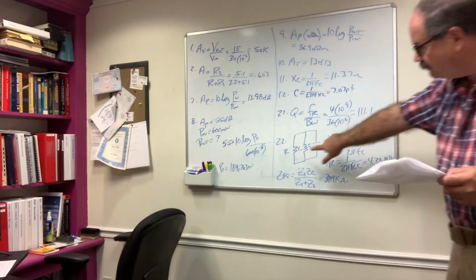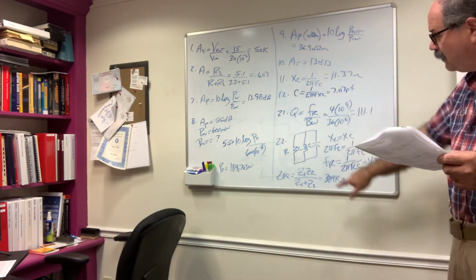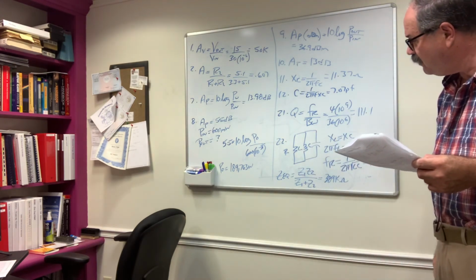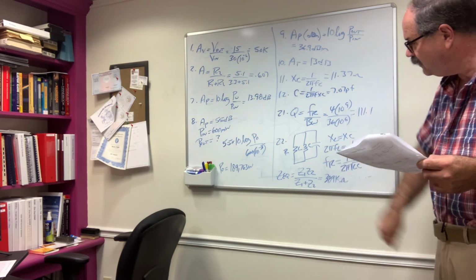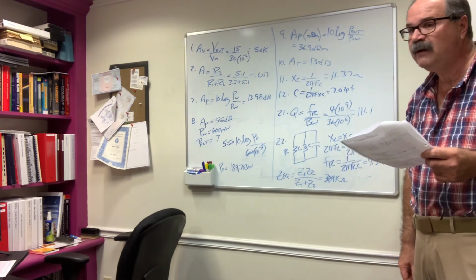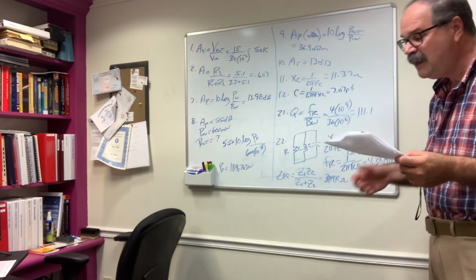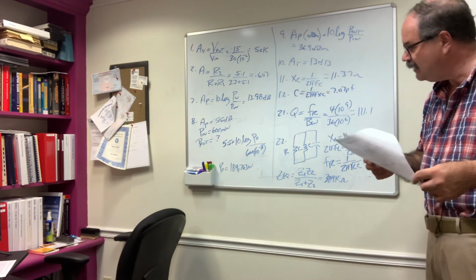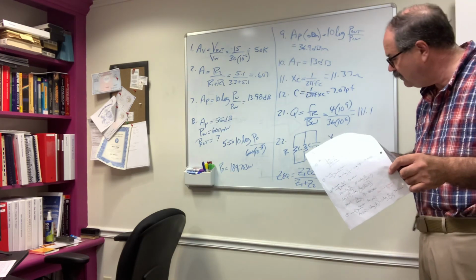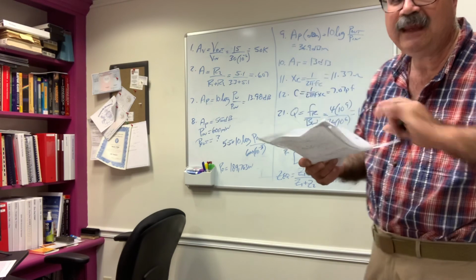At resonance, the value of resistance disappears, so the equivalent impedance of this circuit, Z1 times Z2 divided by Z1 plus Z2, I plug those numbers in. I should get an overall impedance of 389 k ohms.